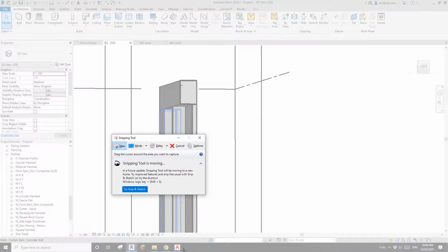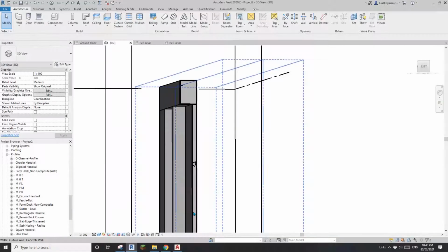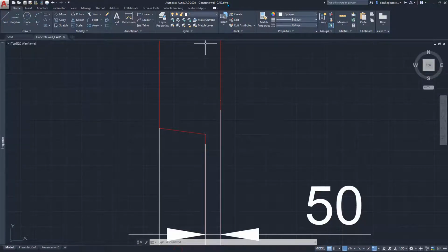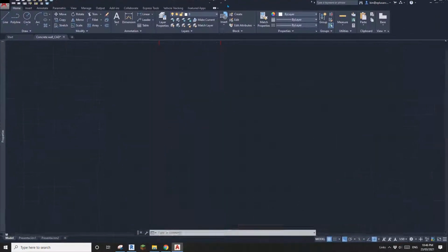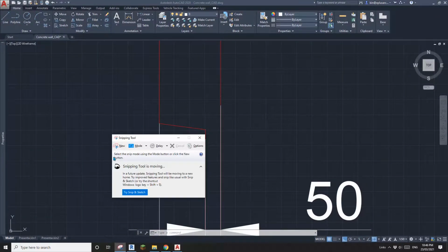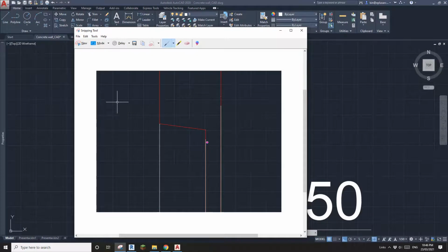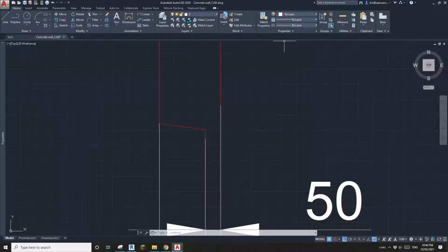It can't, hang on, let me just drag this to here. Okay, so do a screenshot of this. Now this time the mullion stops there, and then we're just going to model this curtain panel to look like this. Okay, so let's do it.